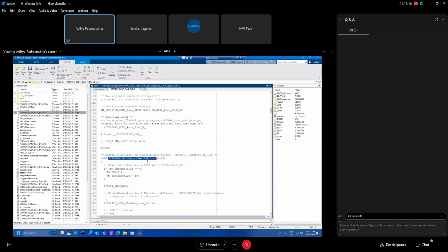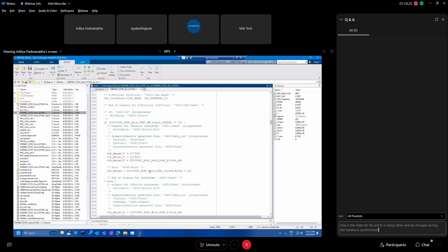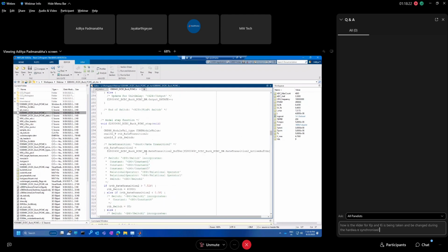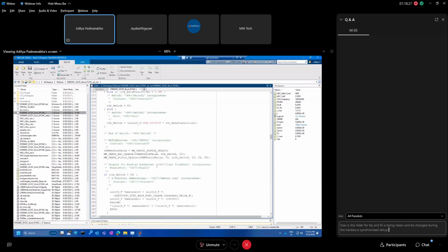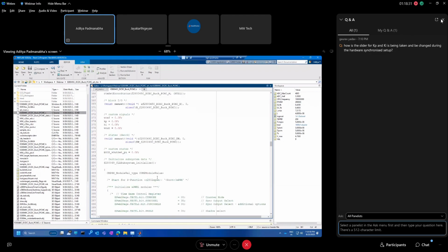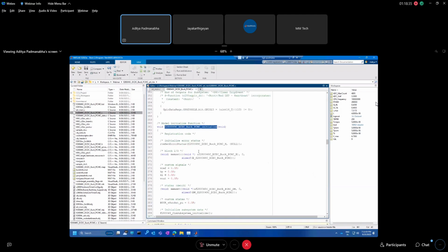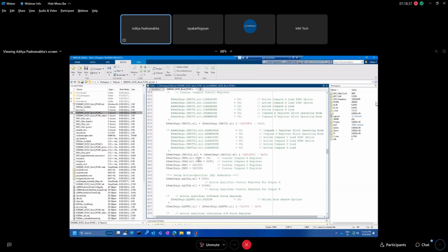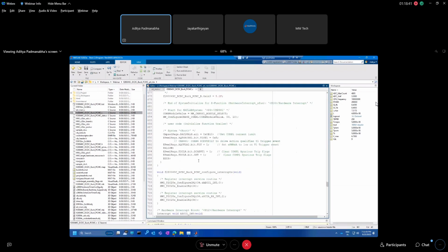So this is our ISR code. This is our step function, which has the base rate functions, whatever is running. This is our initialization function. We have enough comments which clearly indicate which subsystem generated which piece of code. So this is the initialization code containing ADC, PWM, comparator.